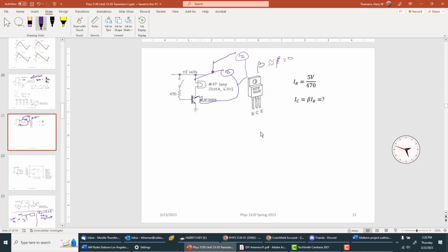And one thing now, I've got 10 amps running for this. I have to remember not to leave this on too long because I could cook on it. It's not quite so warm just yet. But notice what happens when I open this thing. You see that? When I close it, there's no spark. But when I open it, that's because it's an inductor, and inductors are flywheels. And this is not that heavy duty of a coil.